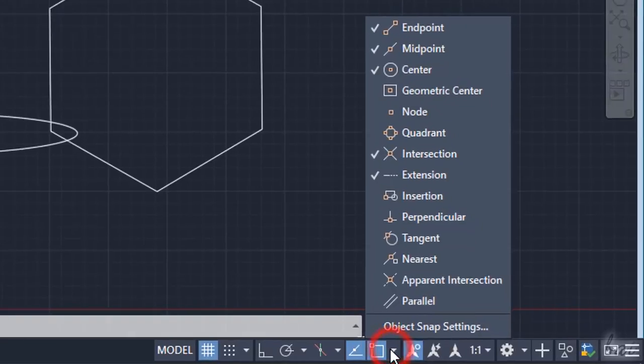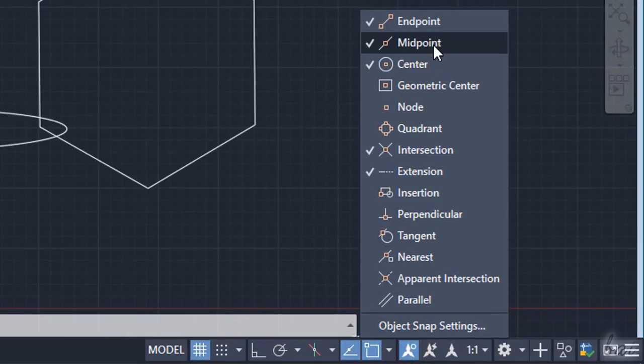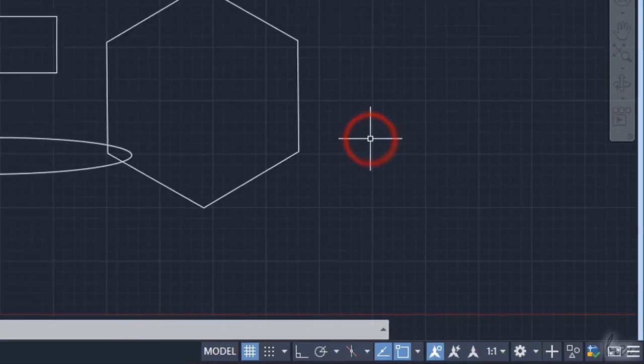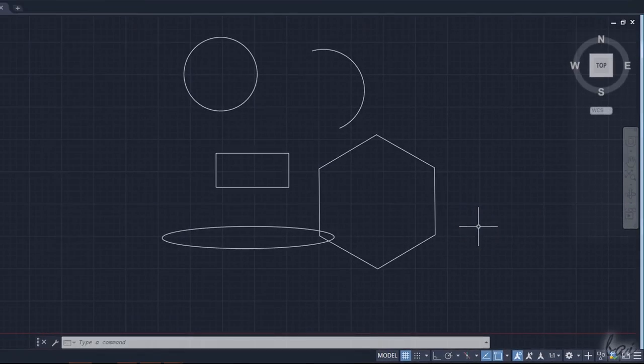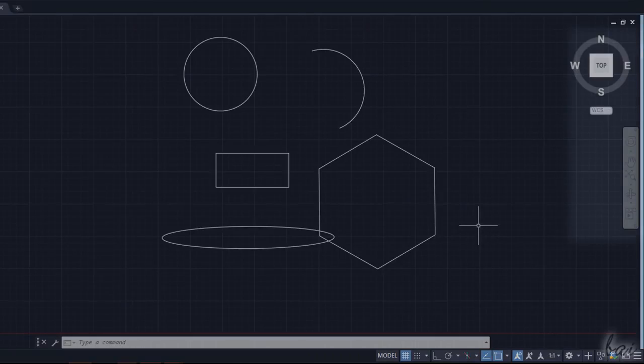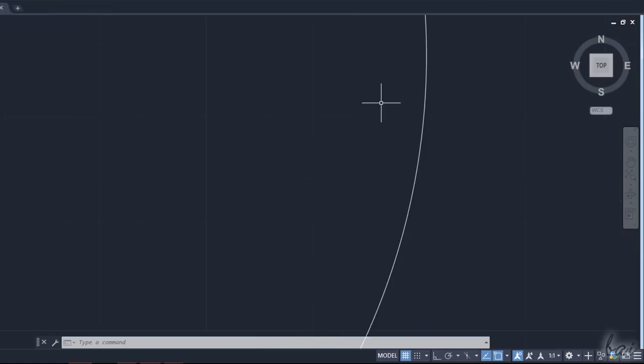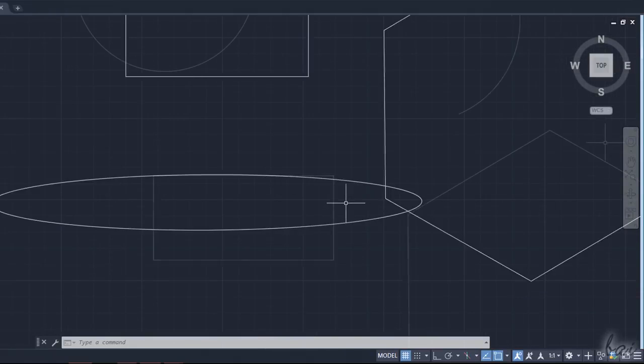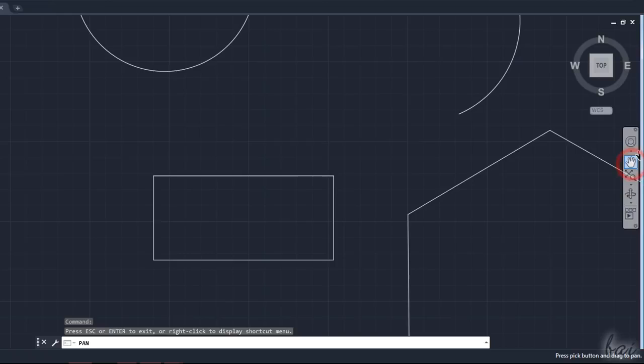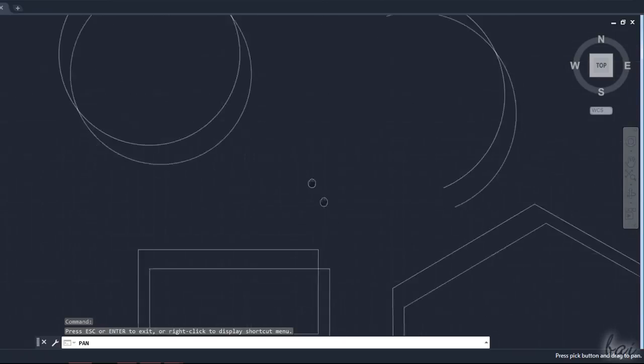You can manage the list of key points and directions to take into account from the list next to Object Snap. You can use the visualization tools on the right to check the status and the results of your drawings. Use your mouse wheel to zoom in and out around your cursor, and the Pan tool to click and drag around your workspace.